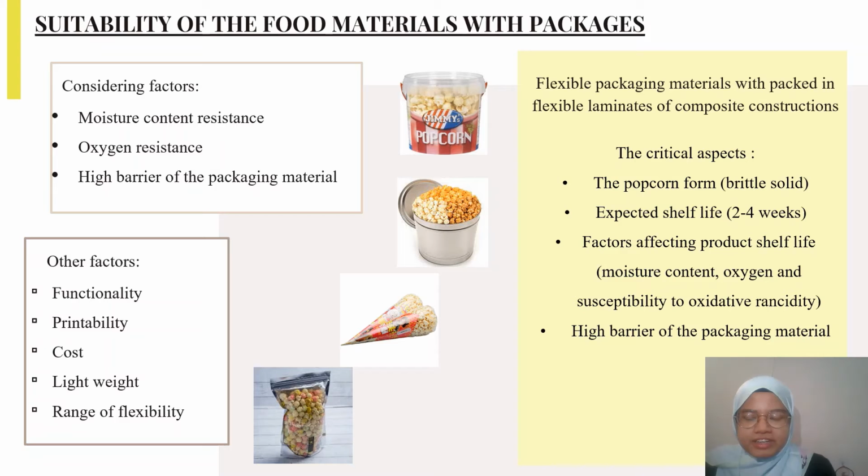The critical aspects that need to be considered when choosing the package are as follows. The popcorn form is a brittle solid, so it is important to have flexible packaging materials. And popcorn often has a shelf life of about 2 to 4 weeks. The factors affecting product shelf life are moisture content, oxygen and susceptibility to oxidative rancidity. And the package needs to have a high barrier, including moisture resistance and oxygen resistance.